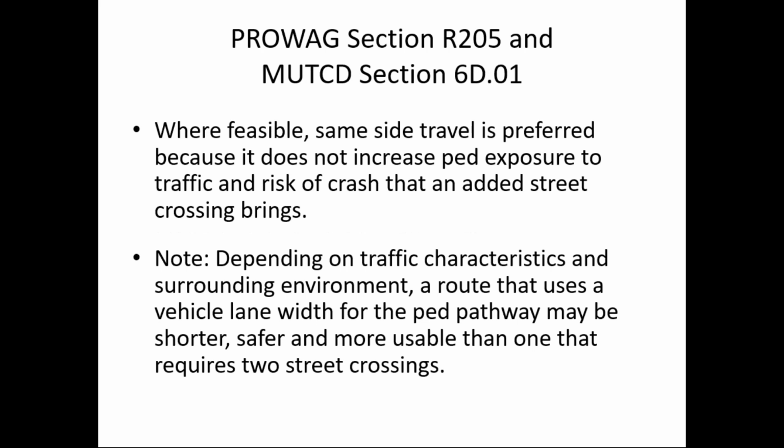Both PROWAG and the MUTCD address this, and desirably, we'd like to keep pedestrians on the same side of the street, because crossing the street not only means additional distance, but there's the potential of exposure to moving traffic, which brings about the risk of a pedestrian-vehicle crash.